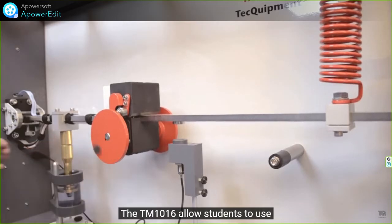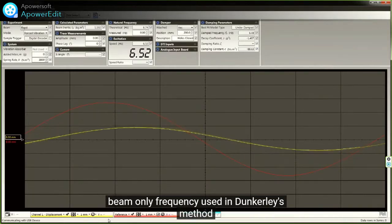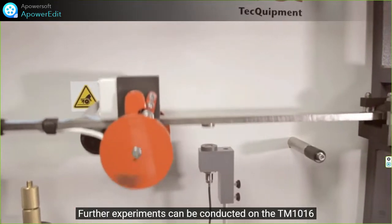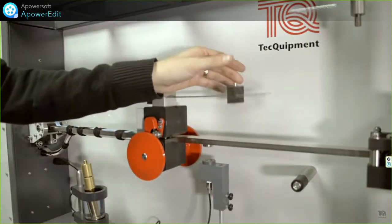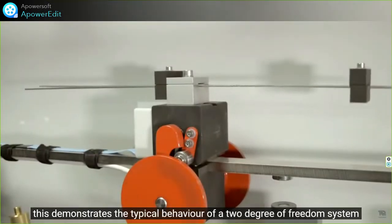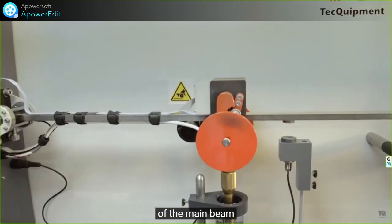The TM1016 allows students to use Rayleigh's approximation to predict vibration frequency and also to find the beam-only frequency using Dunkerley's method. Further experiments can be conducted on the TM1016. Additional mass can be added to the beam. An undamped vibration absorber is also included with the unit. This demonstrates the typical behavior of a 2-degree of freedom system. Students learn how to tune the vibration absorber to eliminate the oscillations of the main beam.